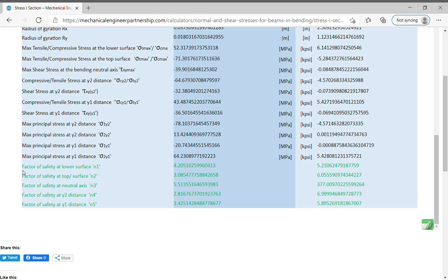The third block is in respect to design factors in longitudinal sections with maximum absolute values of stresses. Choose the minimum value for design calculations. Design factors are expressed in terms of a stress and a relevant strength, and expressions such as strength divided by stress. For values smaller than 1 failure will occur.